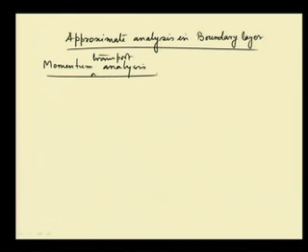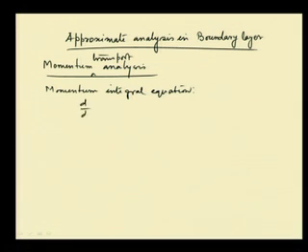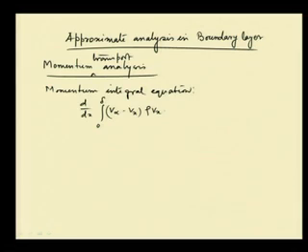For that, our momentum integral equation, which we already discussed in the last class, is d dx of integral 0 to delta, where delta is the boundary layer thickness at any point x, of (V infinity minus Vx), where Vx is the x directional velocity and V infinity is the free stream velocity along x direction, into rho into Vx, where rho is the density of the fluid, dy, and that is equal to tau w. This is the equation we have developed.